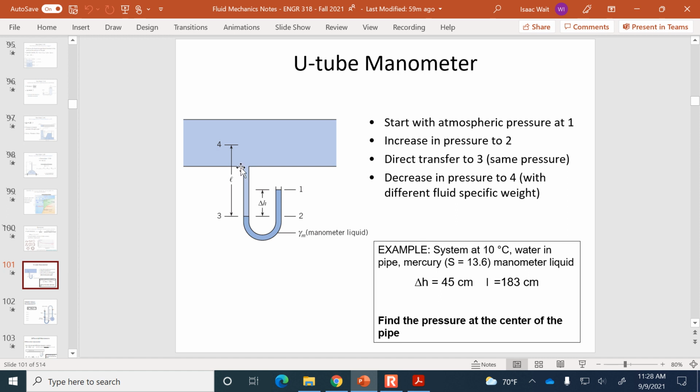Technically, the hydrostatic equation isn't what applies when you have flowing water. So if this is a pipe, like this big one up above, if there's water flowing through this pipe, we really shouldn't be applying the hydrostatic equation from this part up to there. I mean, it's still true that the pressure is going to be decreasing as you go up through the pipe, and it's okay-ish to apply the hydrostatic equation vertically in a pipe, but you couldn't apply it if you were moving horizontally. Because when you're moving horizontally, like in the direction of flow, that's when the effects of pipe friction really kick in.